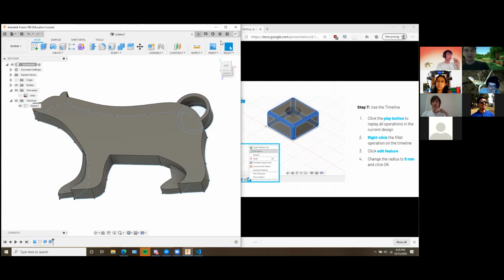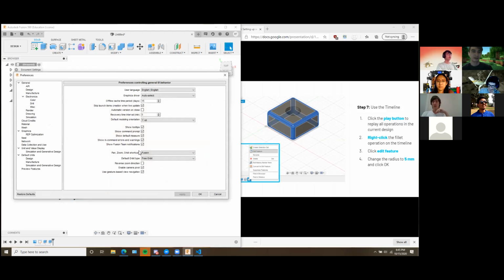I'm not sure if you can change it specifically. I had the exact same issue, so I messed around a little bit. The SolidWorks option gives you orbiting with your middle mouse button, but instead of shift plus middle mouse for pan like it is in Blender, it's control and middle mouse. Okay. And your shift plus middle mouse becomes zoom. And I don't see any way to change that, and it's really irritating.